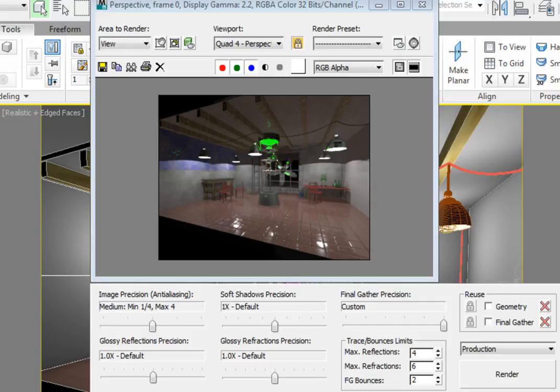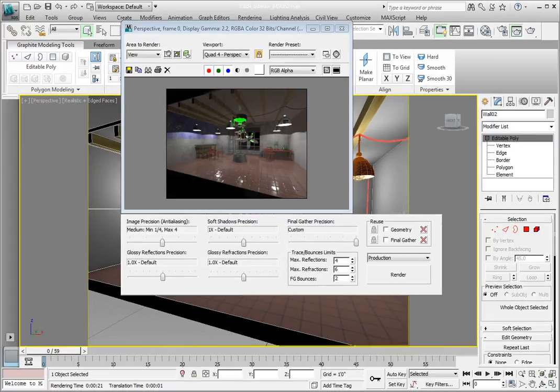You'll also notice that the noise pattern is the same. All we've done is change the color in the color number 1 parameter of the noise map that we modified to become our concrete. We've created a multi-subobject material with 2 materials. Any polygon with material ID number 1 gets the gray concrete, and any polygon with material ID number 2 gets the blue concrete. This is a very simple process that provides a very flexible workflow. Press Ctrl+S to save your file.